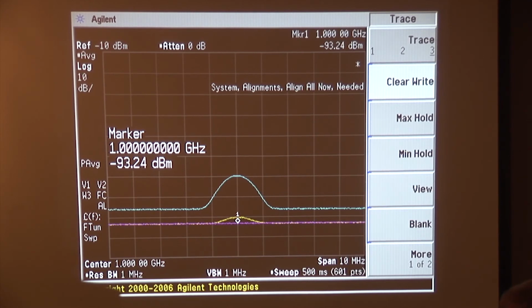Okay, so now I've just cranked in 16 dB of RF attenuation. I'm going to turn the amplifier back on again. Ha! Came pretty doggone close. And so now we're back to having pretty good dynamic range, and also because this does have a little lower inherent noise figure, a little better signal to noise ratio. So that's getting close to being kind of optimized.